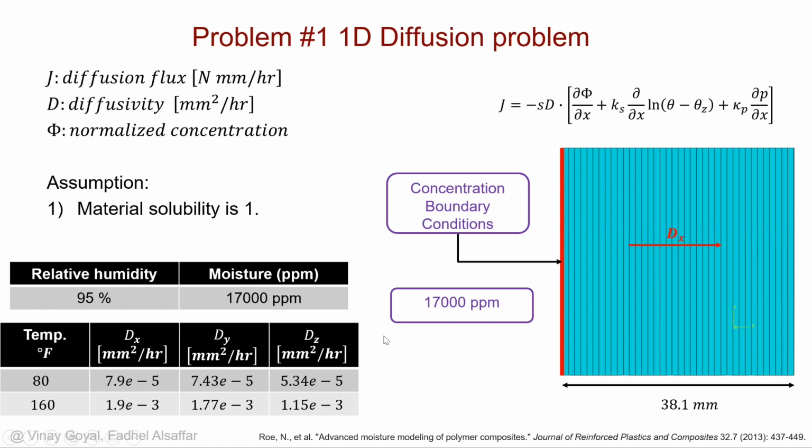And we assume that the temperature is changing within that environment, and we add that effect of temperature change, which changes the diffusivity of that material. That diffusivity is accounted for by this value, so we entered this value and added a temperature dependent step. And then we added another step as a predefined.